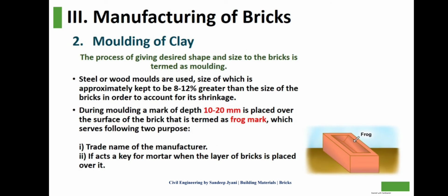Molding of clay. The process of giving desired shape and size to the brick is termed as molding. Steel or wood molds are used, the size of which is approximately kept 8 to 12% greater than the size of the bricks in order to account for its shrinkage.